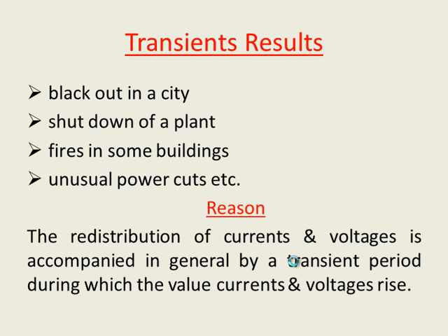Now, generally, a power system is considered as made up of linear impedance elements of resistance, inductance and capacitance. As you have already studied in your previous semester, when we model a transmission line, it is actually resistance, inductance and capacitance. If it is a short transmission line, it is only resistance and inductance, and for a medium transmission line, capacitance is added, and for a long transmission line, there are all 4 elements R, L, C, G.